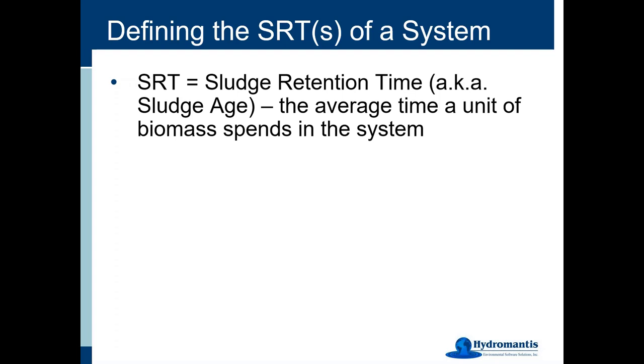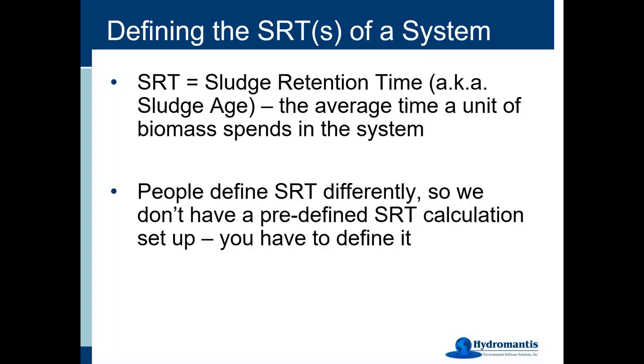So we know that we're going to need 5 days of SRT in order to nitrify at a wastewater treatment plant. But SRT is defined differently. It doesn't have a hard, rigorous definition the way some other parameters do in wastewater engineering. So in a lot of cases, some people want to tailor the definition of the SRT for a particular process problem that they're looking at.